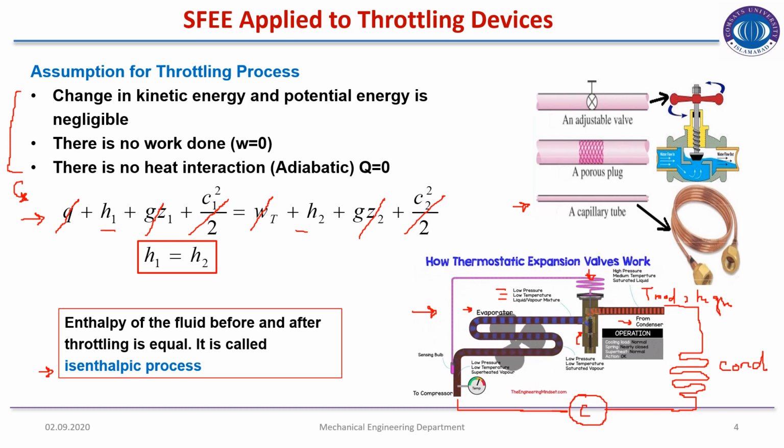We have already discussed this refrigeration cycle, vapor compression refrigeration cycle, in the previous lecture as well. The main focus is that you should know that the expansion valve works as a throttling device. That is, you can read, low pressure, low temperature and saturated vapor are exiting out. So the temperature and pressure both of the refrigerant are very low at the exit of the expansion valve.